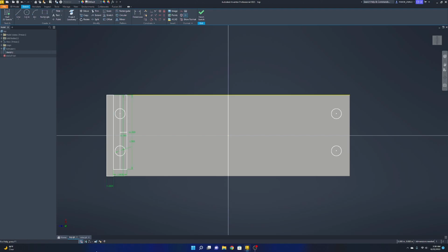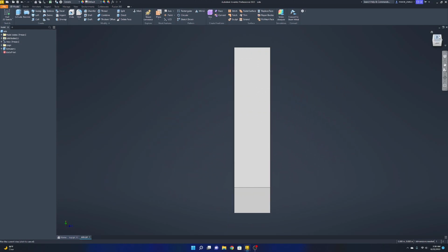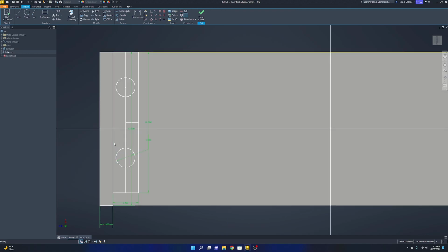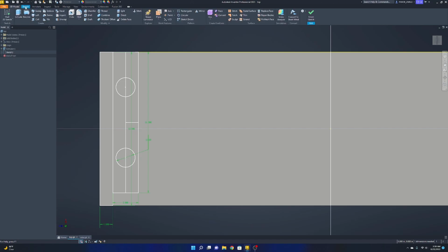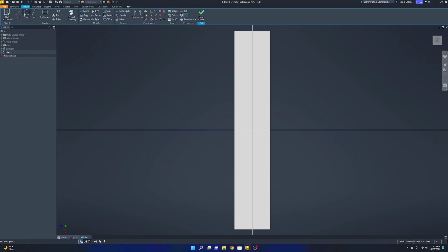All right. So I'm actually going to go over here now and make sure we're actually facing top. And I'm going to actually rotate this here. I'm going to start a 2D sketch on top. And essentially what I want to do now is measure the distance from here to here. I'm going to go to annotate, or I can't do annotate, never mind. I'll go to sketch, and I'll just grab a line, and I'll see how far it is. So it's around 2 inches down. I assume it's also 2 inches here. 2 inches. All right, we'll go back to side, and I'll just kind of go up 2.